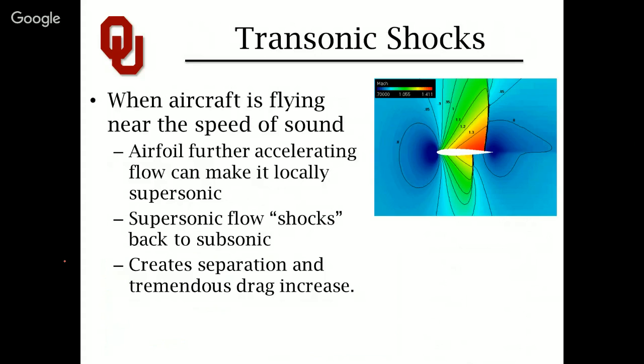But then something interesting happens around the foil. As the flow is accelerated around the top and a little bit around the bottom, you actually see that it goes supersonic. There's not a shock wave as it starts going faster than the speed of sound. It's actually expanding. The flow is expanding and being encouraged around the foil. So you hit a Mach number about 1.3 and a little bit higher. I guess the highest in this region that's indicated by the color swath is 1.411.